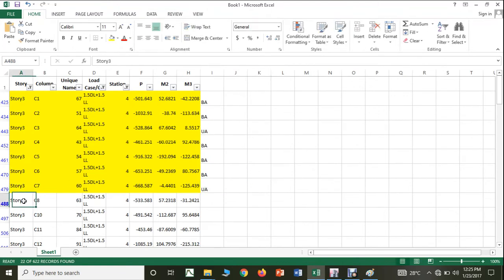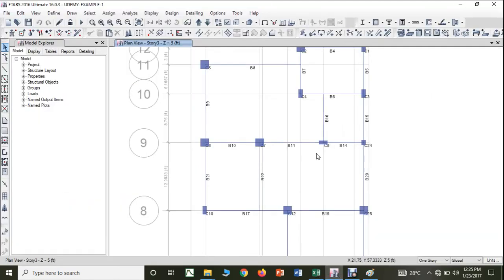Okay, the next you have is column number 8. Column number 8. By looking into this, I can say that I am able to design it as uniaxial, but still, since this area is very high, as well as this entire area is also very high, so this entire load will transfer to this beam and this will come here.